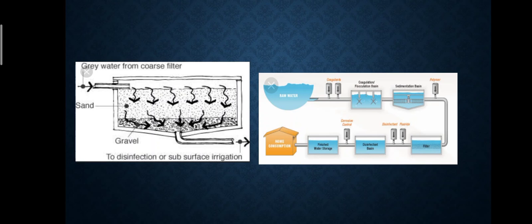The next is secondary treatment. It is again classified into gravel filtration, sand filtration, and chlorination. The gravel and sand filtrations are very similar to each other. The layers of sand and gravel, arranged according to density and particle size, trap and strain particles in the water.